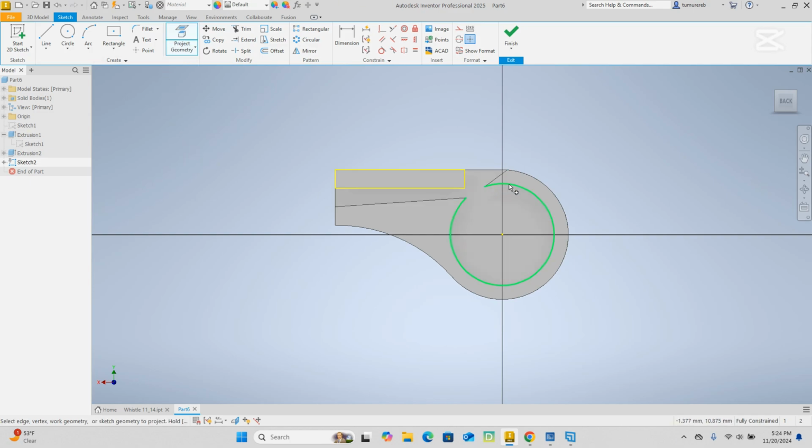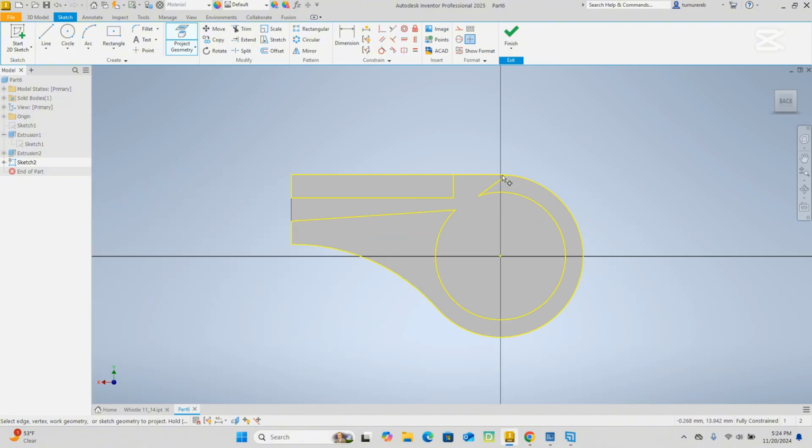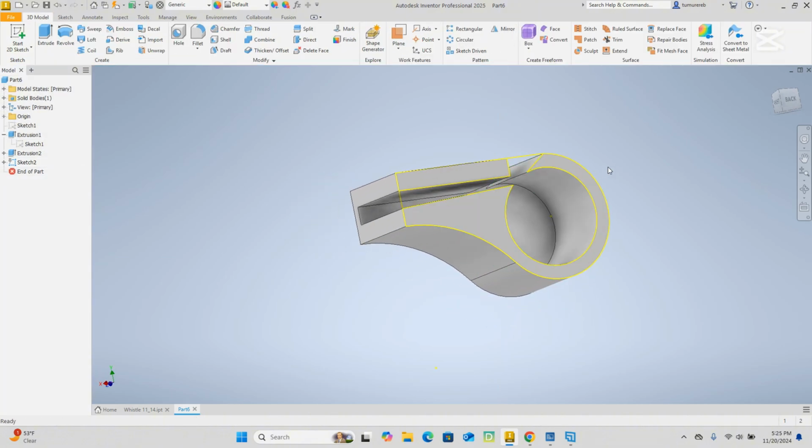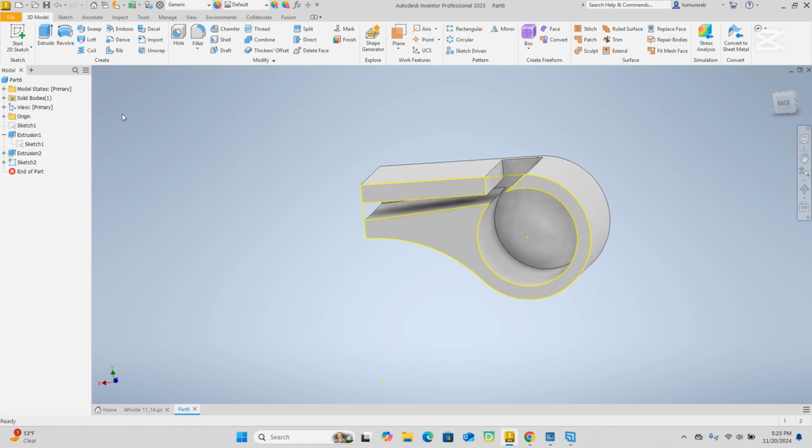Select this file. Select everything you see. Create this yellow outline. This is just the first sketch we started with. See? That's 12. That is 35. That is 9. But we just did it with 2 clicks. We took advantage of project geometry. Okay? Now finish sketch. And I probably missed this. Was there this part? I don't remember. Maybe not. Now let's go ahead and extrude it.